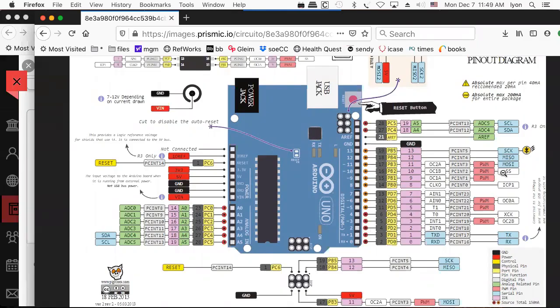This has the MOSI, the MISO, the serial clock, the serial select. There's the PWM pins. That's cool. Let's see what else we can see that's interesting here. Timer 0 and timer 1 inputs for 4 and 5. You can repurpose these things and use them as inputs or outputs. You can use them as digital inputs, just read them. They're digital outputs. Or you can use them as something that'll reset your timer with an external interrupt that's asynchronous. That's cool.